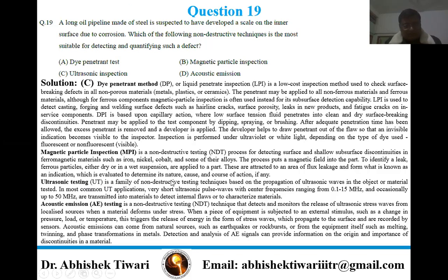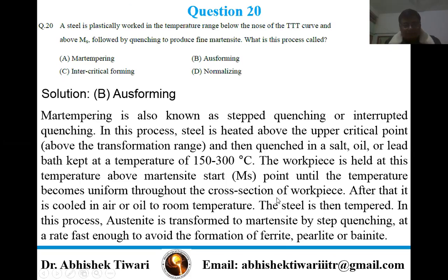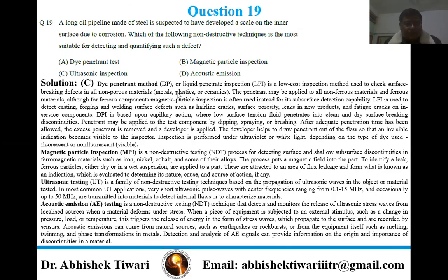Ultrasonic testing is a family of NDT testing based on the propagation of ultrasonic waves in the object or material tested. In most common ultrasonic testing applications, very short ultrasonic pulse waves with center frequencies ranging from 0.1 to 15 megahertz, and occasionally up to 50 megahertz, are transmitted into materials to detect internal flaws or to characterize materials. You can go through other methods also, I'm not going into detail.